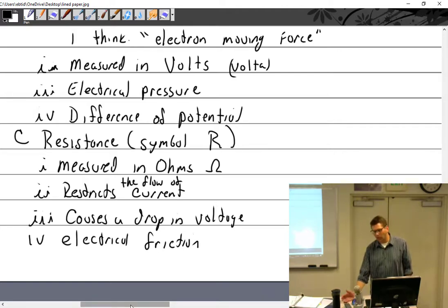Carbon is one of the things that you use often. You can even make a variable resistor. A variable resistor is carbon stacks. You put these carbon stacks in something and push it together really hard, and there's a really good connection, so you have little resistance. Then they relax the pressure and get space between them, so there's more resistance.